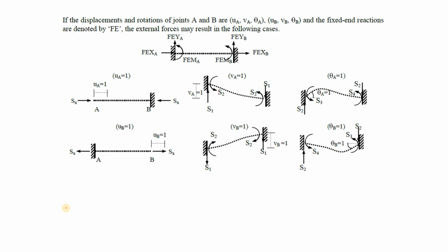Now if the member had some forces, not on the joint but on the body of the member, so this is member AB, let's say the member had some sort of load, a UDL, a distributed load, on its body, or perhaps it had a point load on its body, right? So how are you going to tackle that load? We're going to have to mention that load as well. This is actually also coming from the moment distribution method or the Hardy-Cross method, where we have seen that. Let me just erase this and we'll continue.